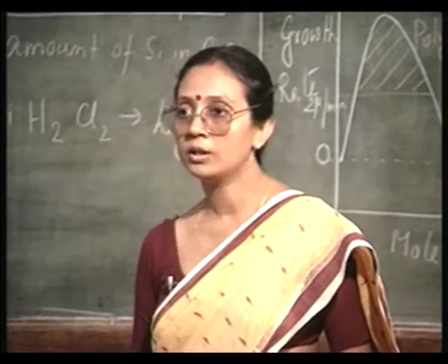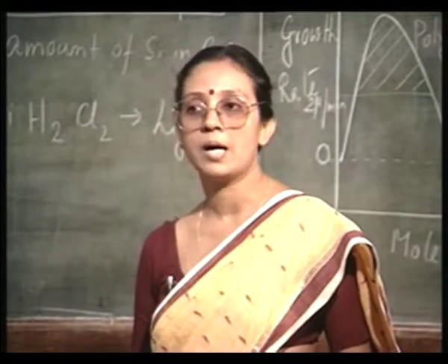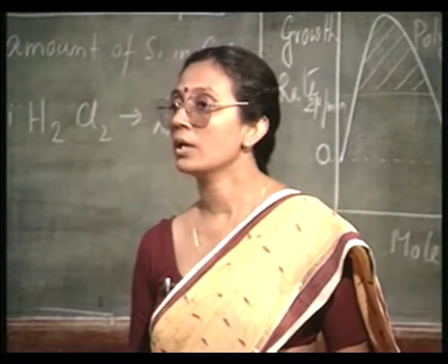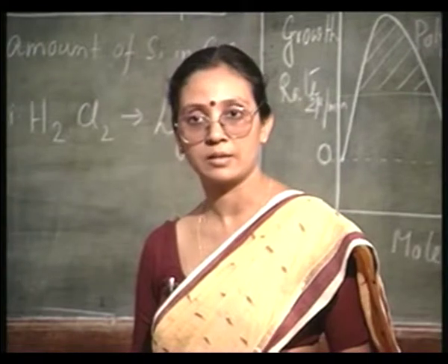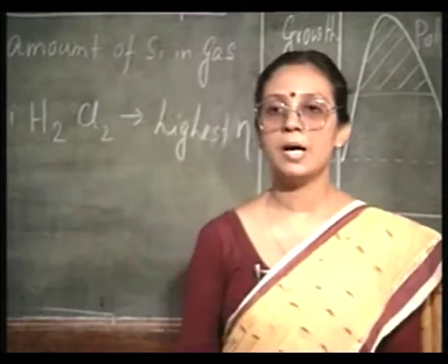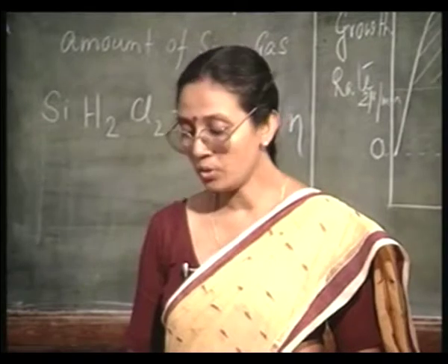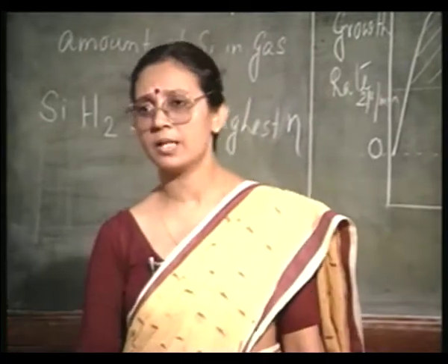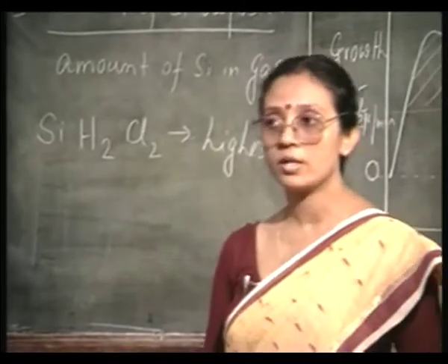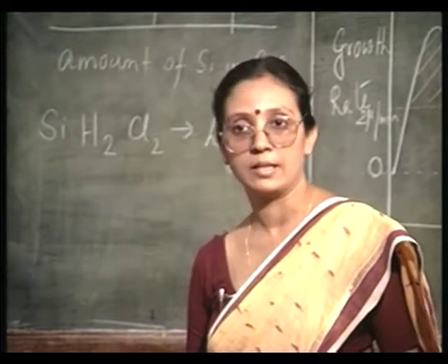Therefore, all silicon epitaxial reactors must have an excellent venting system, otherwise you are not allowed to use that epitaxial reactor, it is hazardous. All of them must have an excellent venting system in order to take care of HCl. Remember, it does not matter which one you use, SiCl4 or SiHCl3 or SiH2Cl2, you always have a lot of HCl as byproduct.